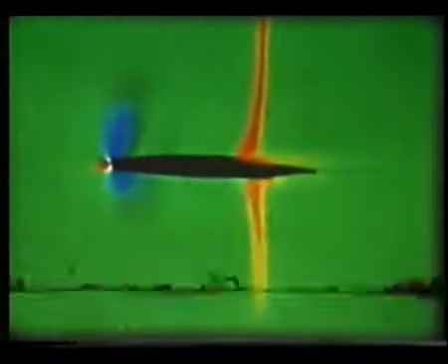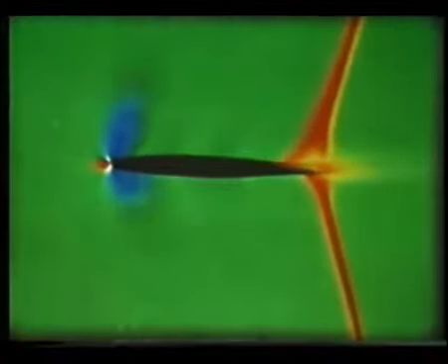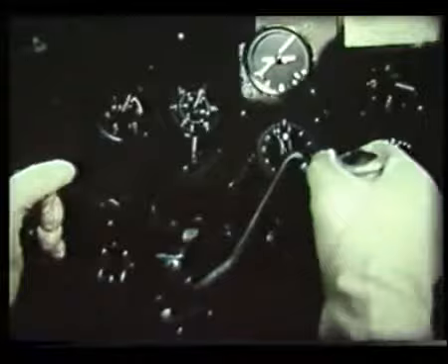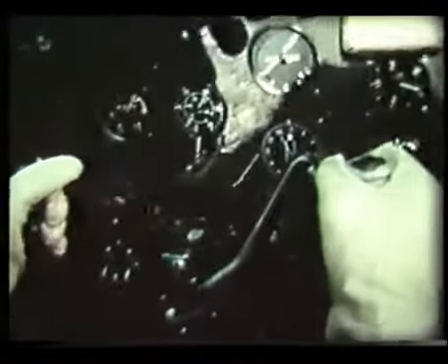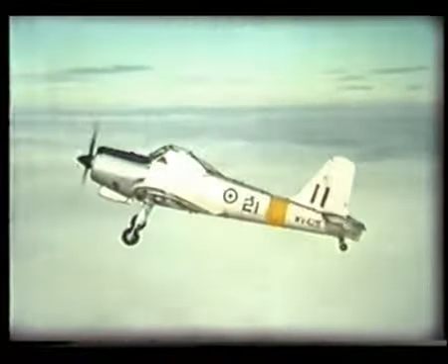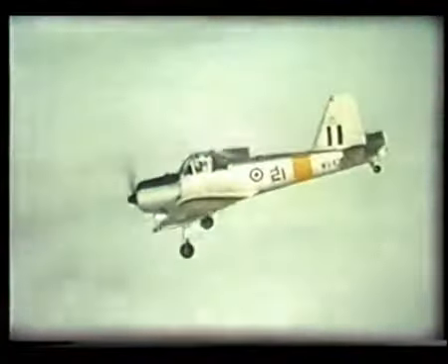But it is flow separation that causes most of the troubles in the earlier part of the transonic range, when the shocks are moving back and causing separation. Once the shocks have reached the trailing edge, separation is much less. It is flow separation that causes the shock stall, so called because the effects in flight are rather like the normal low speed or high incidence stall, also caused by separation. The first shock stall trouble is a sharp rise in drag.